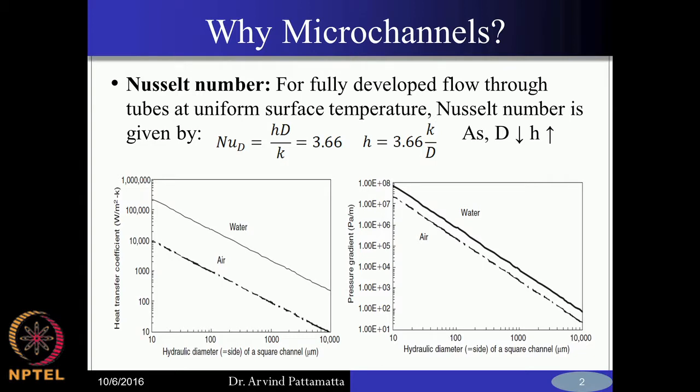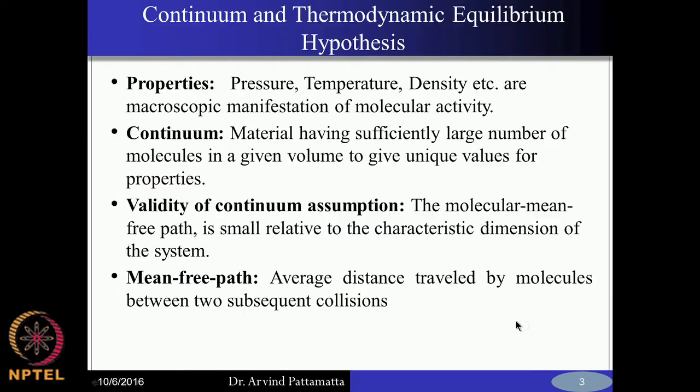So, we cannot directly jump from this to this and claim that this is very effective from a hydrodynamic point of view, because your pressure drop is going several orders of magnitude higher than that of the heat transfer coefficient. But nevertheless, when you are dealing with small devices and you have to cool them, inevitably you have to use microchannels, and therefore you have to deal with this counterintuitive problem.